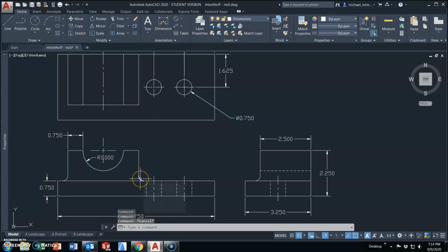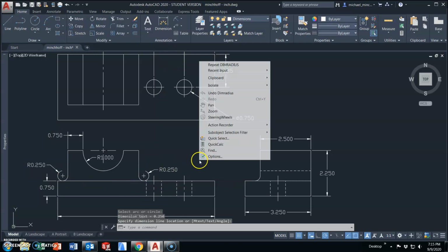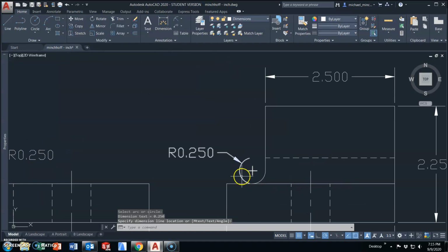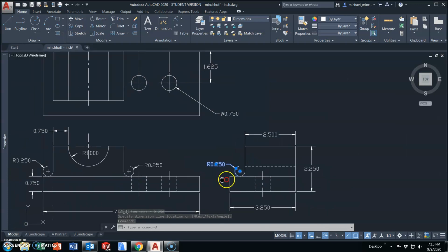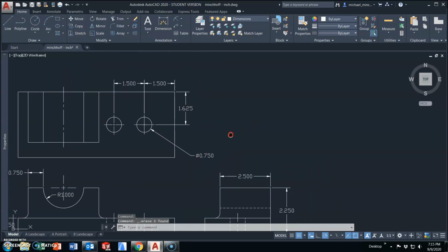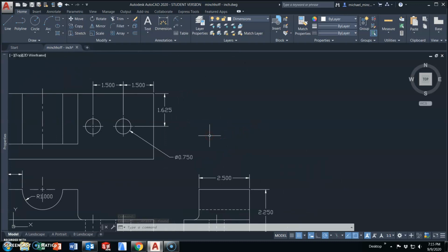The fillets, yes, they are a radius, but just like the sheet that you're working from, if I go and put all of these little radius dimensions on here, it's just a byproduct of AutoCAD, it makes this continuous arc to extend out from the arc. It really makes this confusing. Is this part of the drawing? But dimension notes or radius notes for fillets and rounds is done in a note.